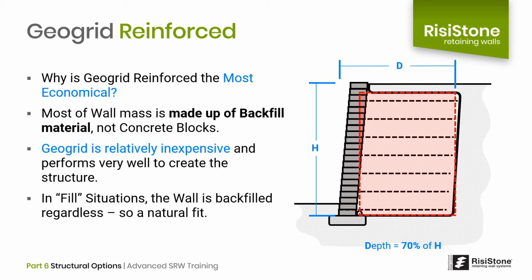In a fill situation where we are adding height to the site or filling the site, we are backfilling to raise the grade anyway, so this is where geogrid reinforced walls are really a natural fit.